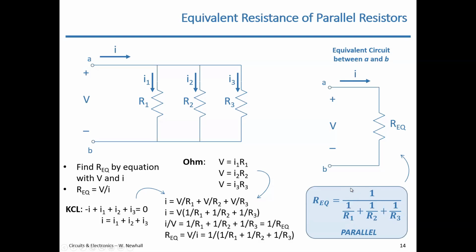All right, a professor in the past mentioned that resistors in parallel are like lanes in a highway. The more lanes, the faster the traffic can move, increasing the current. That's true, right? So let's say you have R1, R2, and R3, and they're all 30 ohms. If I combine all of those in parallel, I think if I do the calculation in my head, I'm going to get 10 ohms.